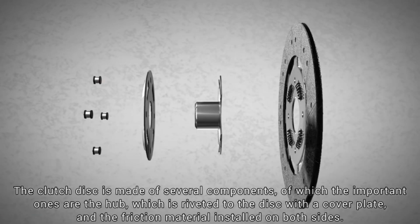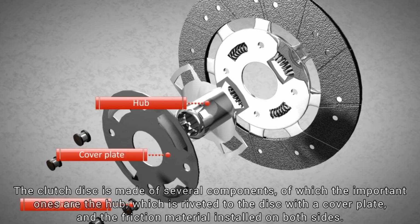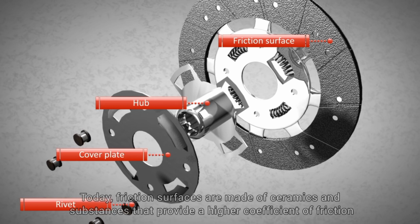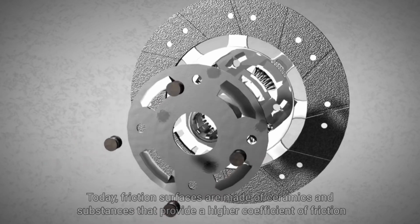The clutch disc is made of several components, of which the important ones are the hub, which is riveted to the disc with a cover plate, and the friction material installed on both sides. In the past, friction material was made of asbestos and other harmful substances. Today, friction surfaces are made of ceramics and substances that provide a higher coefficient of friction.